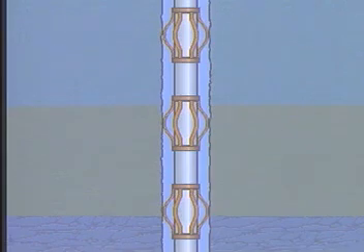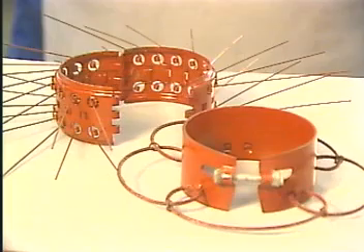Such mud channeling is the predominant cause of cementing failure, and much of a good cementing procedure is focused on preventing this from occurring. Several techniques, which are often combined, are pipe centralization to allow uniform displacement of the mud by the cement, pipe movement, either reciprocation or rotation with scratchers to improve displacement in enlarged hole areas, and the high displacement rates and turbulent flow regime mentioned earlier.